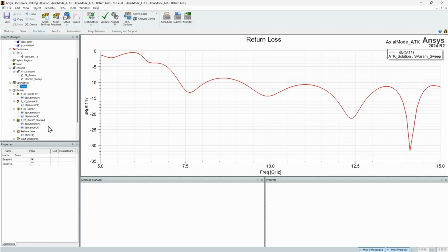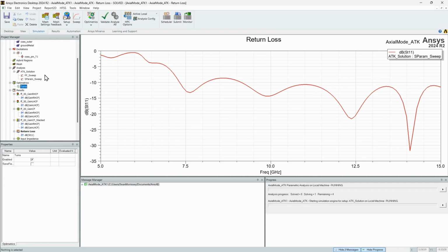And it's always good to validate before you analyze. I know the validation is going to be okay here because geometrically, nothing should be interfering with the values we have selected. So you can already see that we are A-OK to run this. So I'm going to go ahead, right click on turns, and we're going to press analyze.